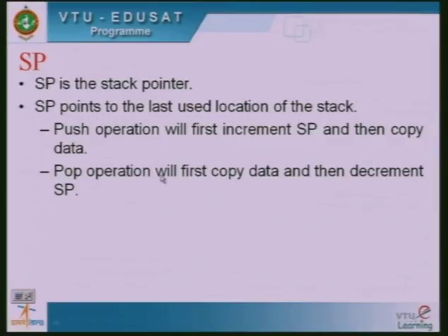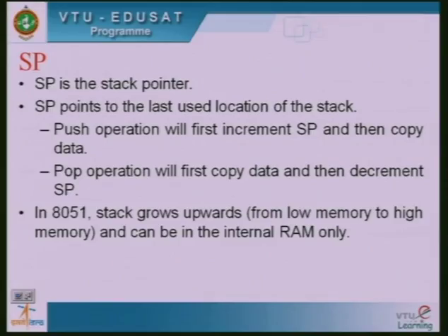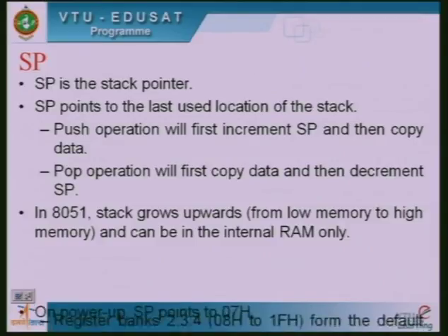Pop operation will first copy the data out of the stack, pop the data out, and then decrement the stack pointer. Please remember, as I showed you, in this microcontroller the stack will grow upwards, from a lower memory to higher memory. You saw the lowest memory address of the stack was 07, then it incremented to 08, 09, 0A, 0B, and so on. So this is how the stack works.